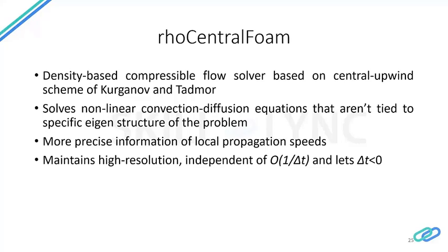rhoCentralFoam is a density-based compressible flow solver. It is based on the central upwind scheme of Kurganov and Tadmor. rhoCentralFoam solves nonlinear convection diffusion equations. These equations are not tied to a specific eigenstructure of the problem. rhoCentralFoam provides more precise information on local propagation speeds.